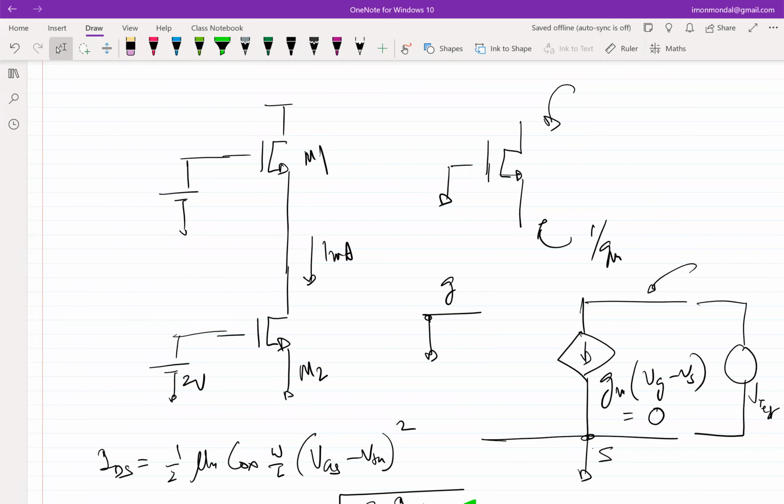As it turns out, when you will be designing, you will be given one current source, just like you will be given one voltage source. Just like you don't use one battery for each transistor that you are making, you will not be using one current source for each transistor that you are trying to bias. So you will have a master current source, and you have to derive everything from that master current source, right? We'll get to how we will derive from the master current source, but for the time being, let's assume there is a master current source. But given that we cannot use one dedicated current source per transistor, what else can we do?